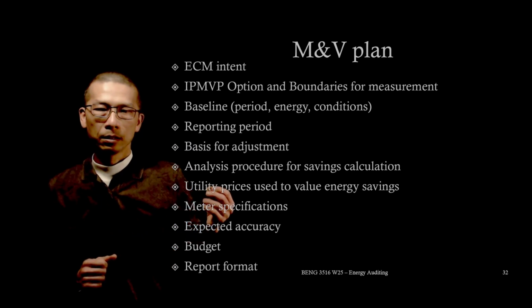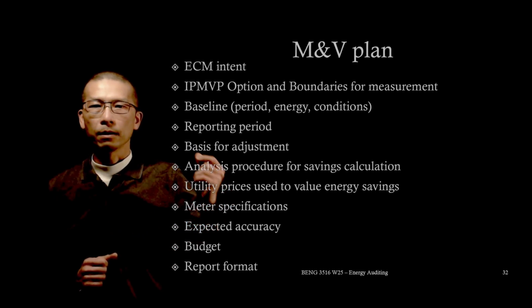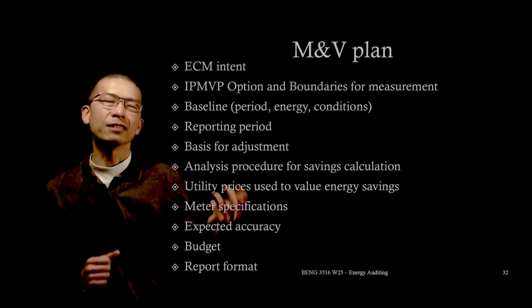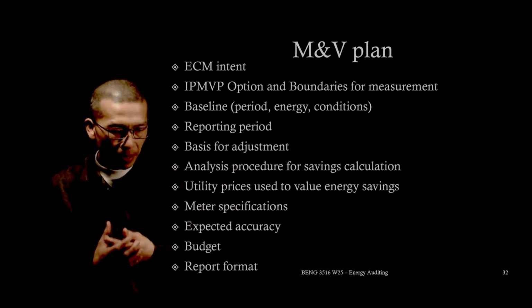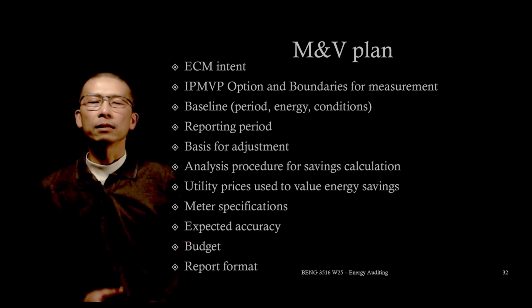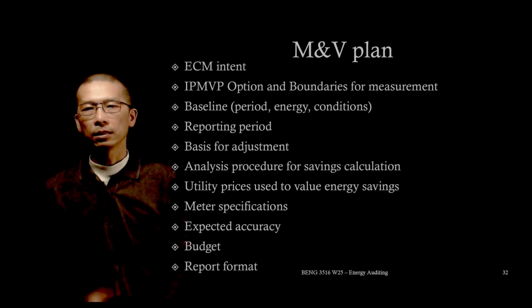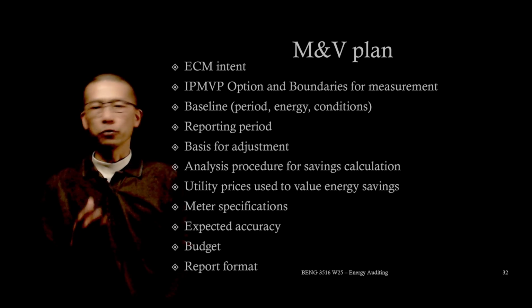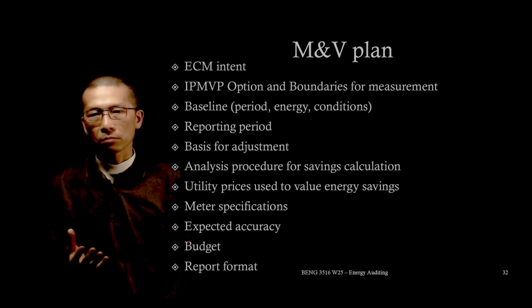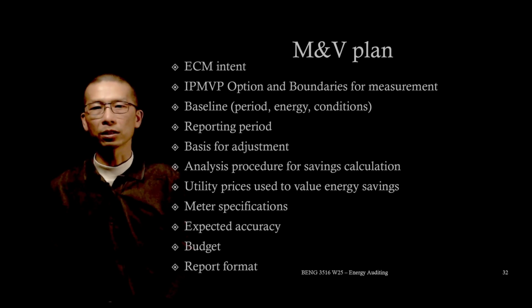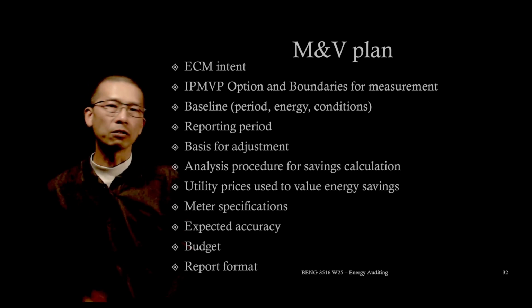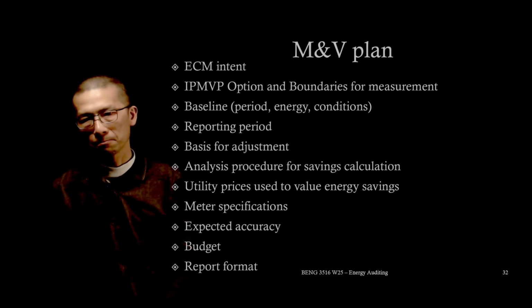Defines the scope, it specifies which part of the facility or system will be measured. Okay. Baseline. It establishes the baseline period and conditions. This includes documenting the pre-project energy consumption, relevant operating conditions, and external factors like weather and occupancy.